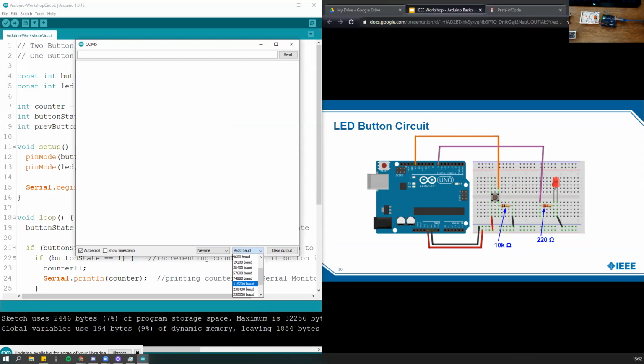Okay, so Eileen, for your board, you're using a Mega. If it has an A in front of it on the pin, so you're saying you're using pin 7. This is a Mega, it would be digital. So you just put 7. It wouldn't really matter. Okay, hopefully that answers your question. Let me know if you have any trouble hooking that up still.